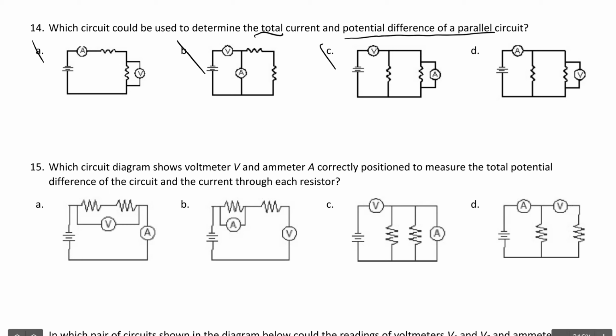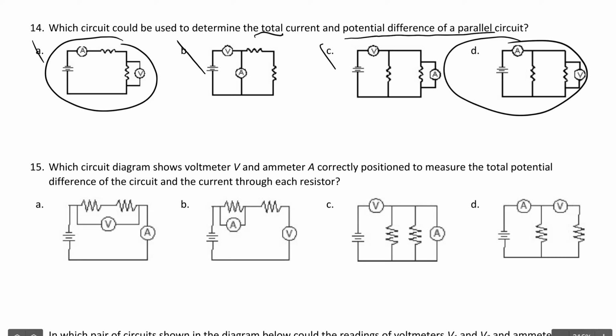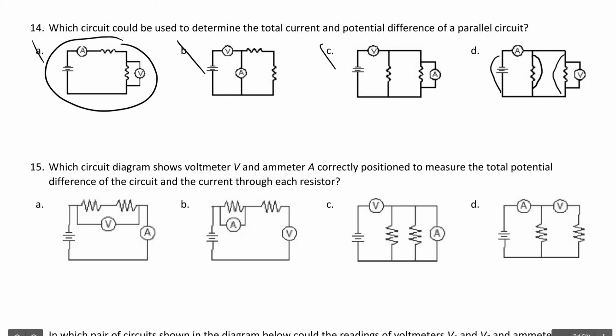Okay, what about this one? Oh, what's the difference here? For D, the resistors are placed in parallel with each other. In part A, the resistors are placed in series with each other. So we have to be super comfortable with and well practiced with the relationships in series and parallel to realize that the voltage across this resistor is the same as the voltage across this resistor, which is the same as this voltage because they're measured in parallel.